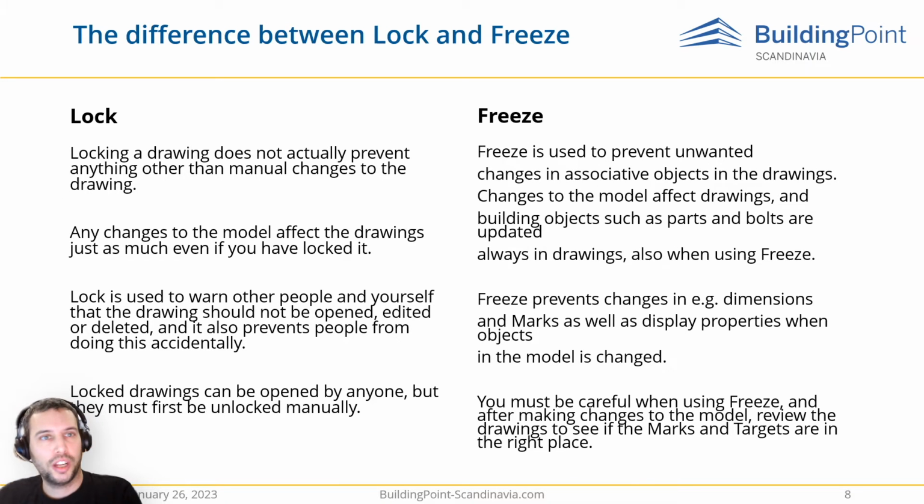Do you know the difference between lock and freeze functions for drawings in Tekla Structures? Locking does actually not prevent anything other than manual changes to the drawing. If you do any changes in the model, the drawing will just as much show this, even if you've locked it. But of course, you need to unlock the drawing first.